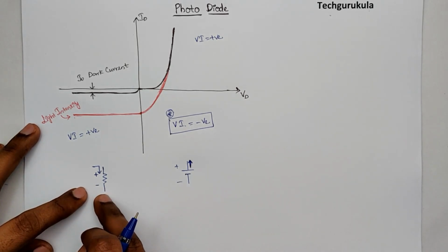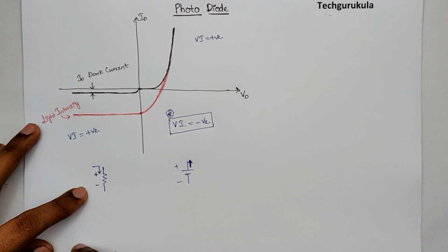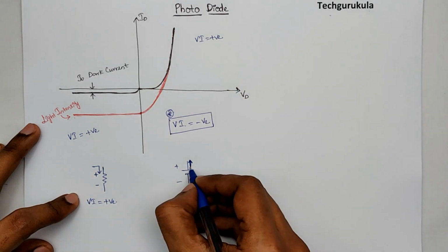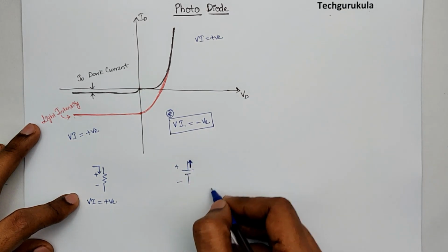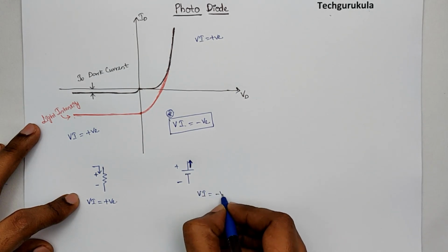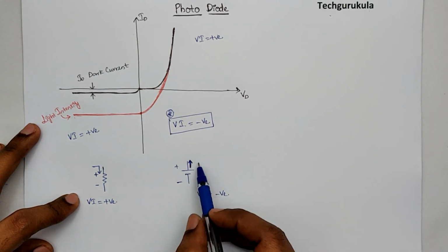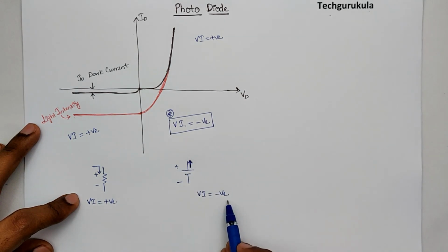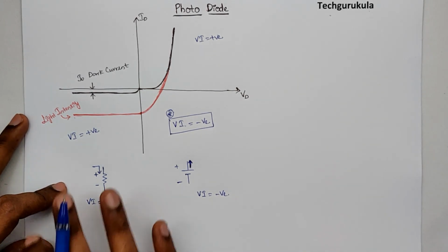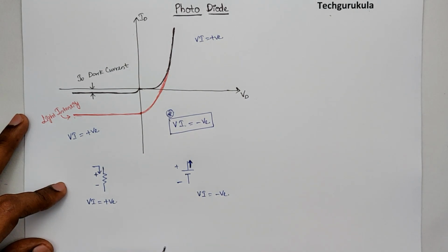So in the resistor case, the current is entering through the higher potential point where V times I is positive, and when current is leaving from the positive terminal and entering into the negative terminal, V times I is taken negative. So it means the supplier's power is negative and the absorber's power is positive. Hence, usually in network theory, we say the entire power in a circuit is zero because there are sources whose power is negative and there are elements absorbing the power whose power is positive.